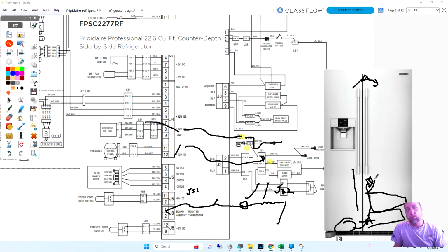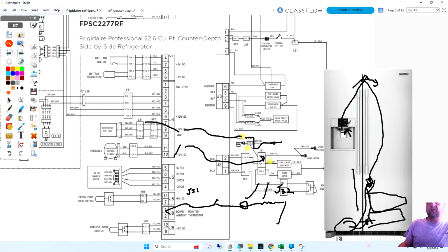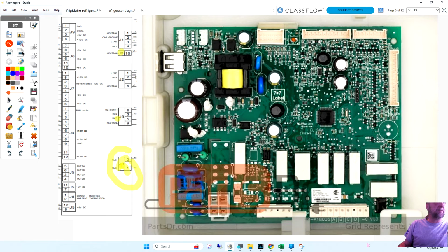Another thing on the Whirlpools is that if the flap in here doesn't close all the way, warm humid air gets in, goes to the damper, and then comes back here, and I've seen the channel inside this wall freeze solid with ice. So you go there and there's nothing blocking it, but the humidity that was coming in through this door flap was causing freezing on the return air. So that's something you guys need to look out for.